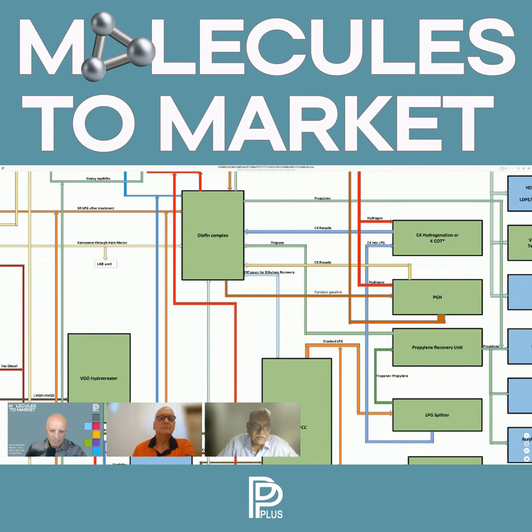Now come to Petro FCC. UOP does not really have a Petro FCC so far. I haven't seen their process give me yields of 21% or so, but they have a high severity FCC process. Their yields are also good, but never as high as Axens or Technip, because Technip has the right sort of technology, that is Stone and Webster earlier on. So Technip is the one who's got a fantastic technology here. But if one wants to go to UOP, UOP has as good a process.